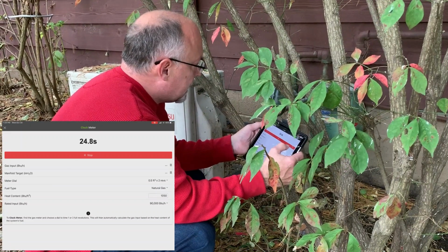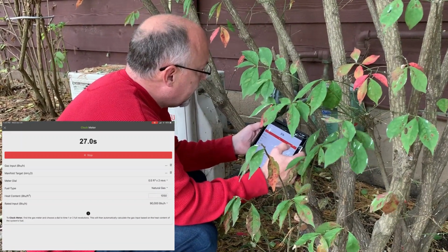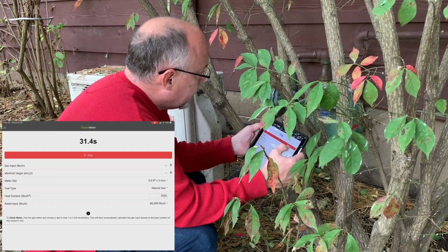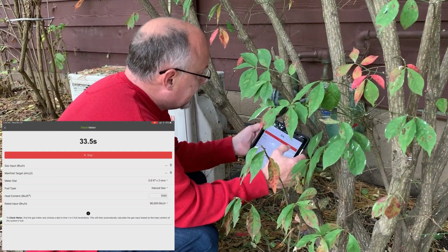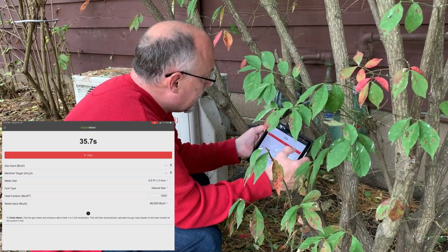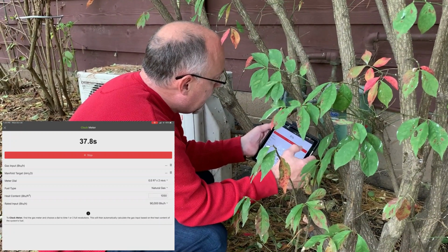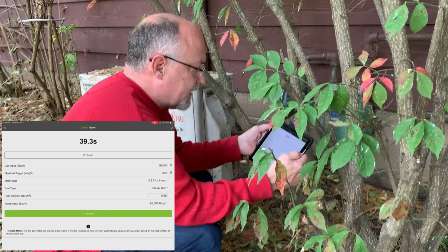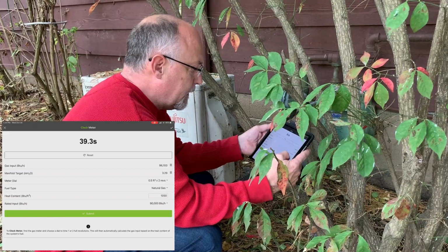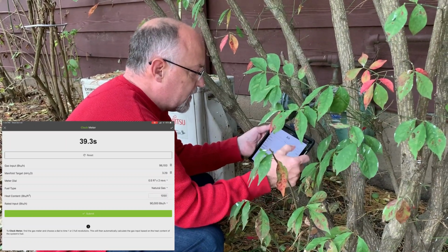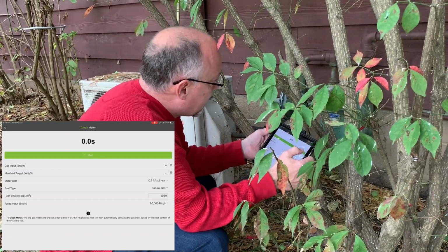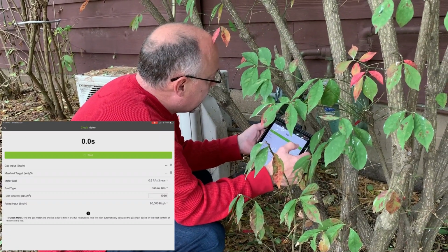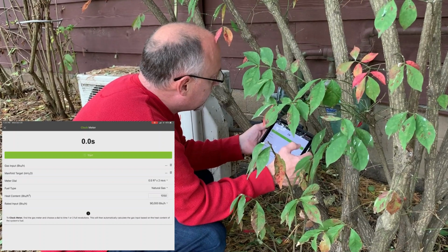The reason you let it go around 2 times is so that we make sure that we're getting an accurate reading. So it sort of averages those 2 readings out here, and it's coming around to the top and mark. So we're at 39 seconds. We're at 96,100 BTUs of input. I can submit that, or I can reset it. So I'm going to clock it one more time because I'm curious if it's going to clock the same, because I know I had the gas pressure closer than that.